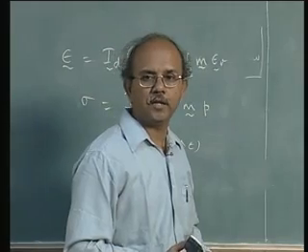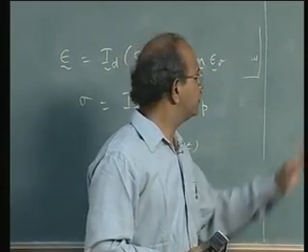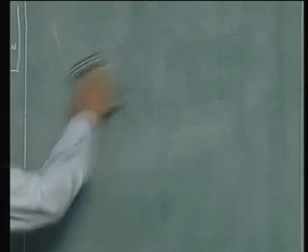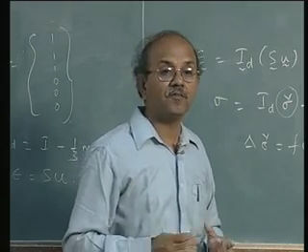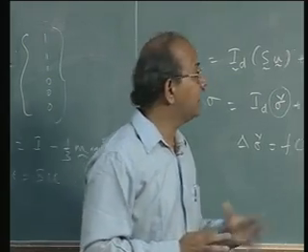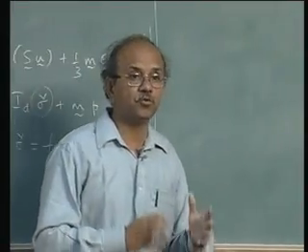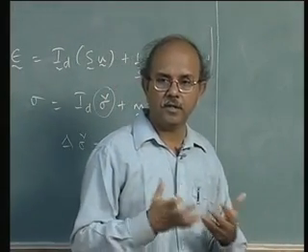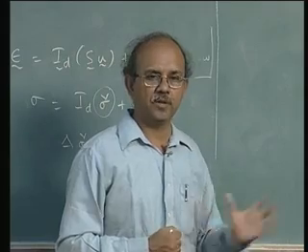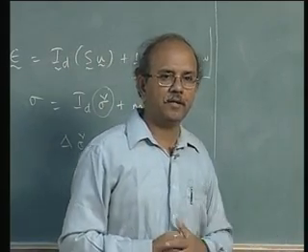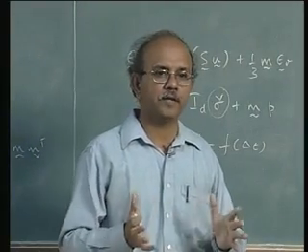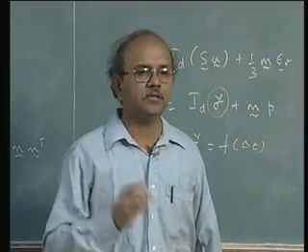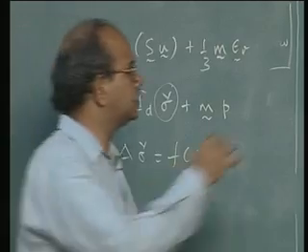And especially in a situation like plasticity, you may not be correct to go to a variational form straight away and write it. It may not be mathematically very correct, because you don't have a strain energy function. Most of the variational forms are written in terms of strain energies, and you do not have a strain energy relationship like what you have for elasticity, so you may not be very correct. But the next step, where we write down the Galerkin form or virtual work form, is fine for many of these things. So let me write down the virtual work form for this.